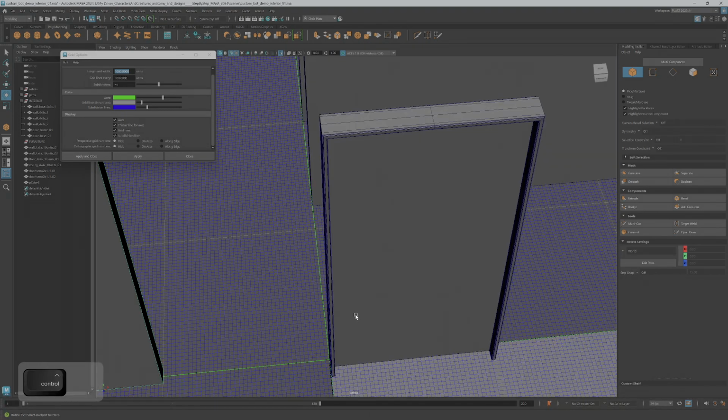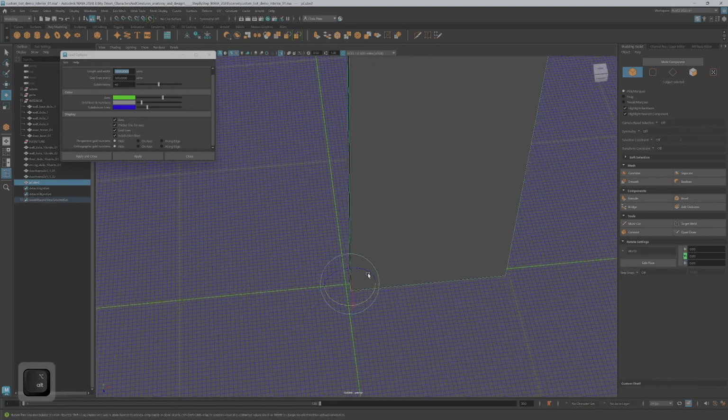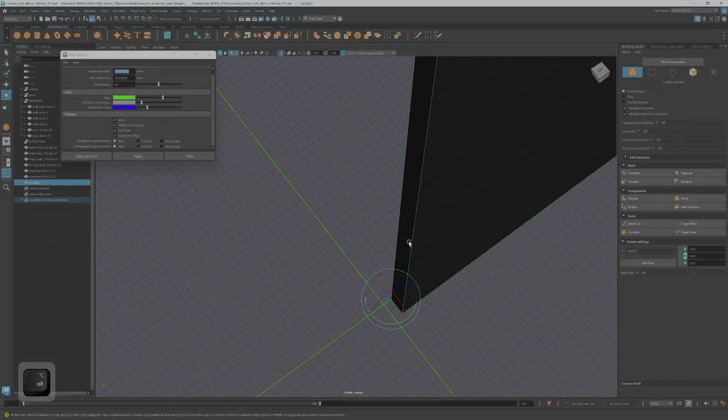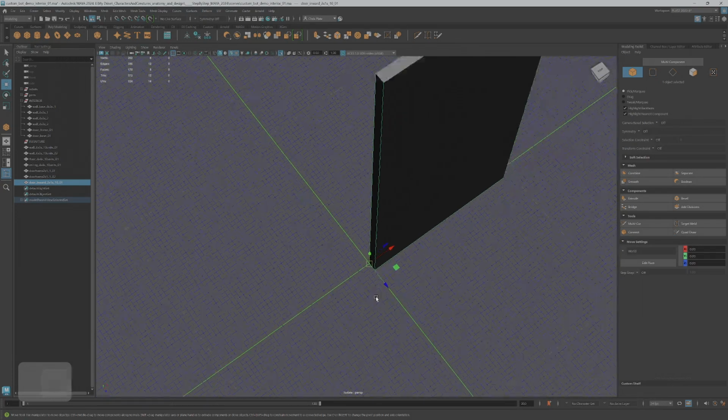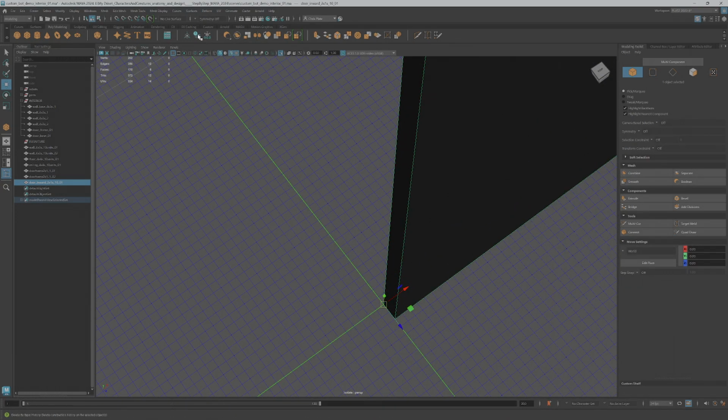Isolate that door for a moment. And if we want that to be centered to the world, go to move and just hold down X, bring it over, make sure we have door. And then you could do underscore inward door, right? Underscore, and we could do a 2 by 1 by dot 10 ratio. So we just kind of remember what your ratios are on there. Okay, oh yeah, freeze, delete history. There we go. So this will go inside of our furniture.